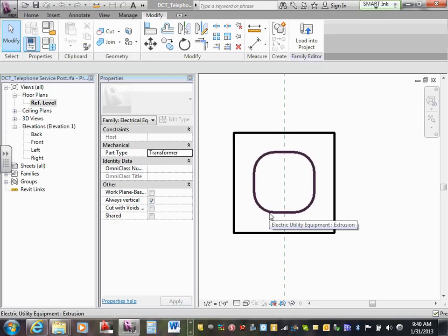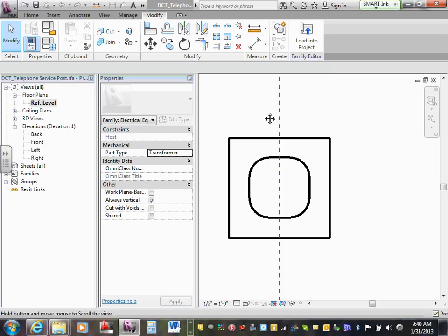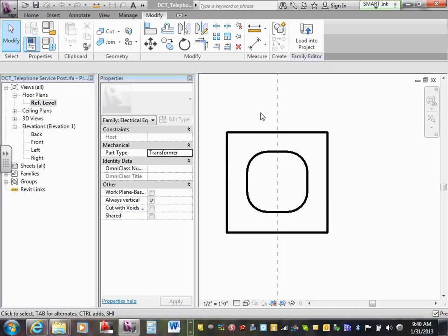I would probably model it 3 inch by 3 inch, so it is the actual physical size, because this is Revit, this is BIM. You kind of want things to be represented like real life. But then in plan view, I'll maybe create a nested annotation symbol, so that in plan view you don't see the physical object, you just see the nested annotation symbol.